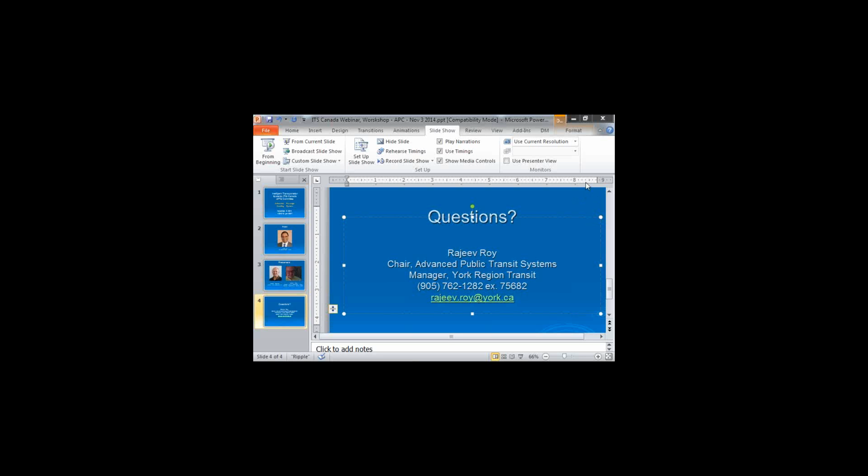Okay. Yeah, basically, because we have the IRIS sensors installed as well on the Dart LRT, and the specification, what we are relating to our installation process is basically that we count, and we have the IRMA 3D installed, so we have 500 passengers, we verified the data with 500 passengers, and this is based, as I described earlier, we're using the VDV standard, or IRIS is related to that standard, what they experienced when they started in Germany, and this was presented, specified as well with Dart, that we use this standard to verify the data.